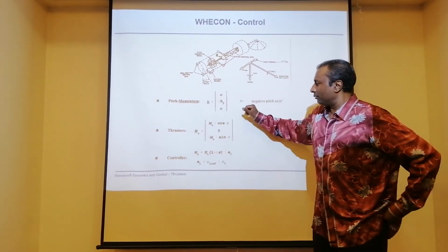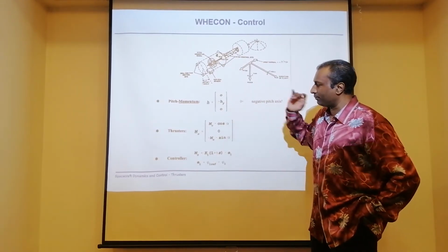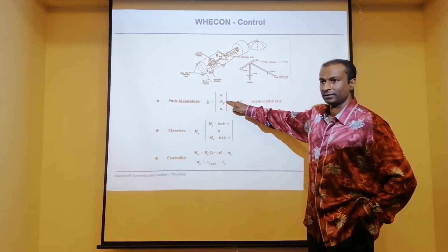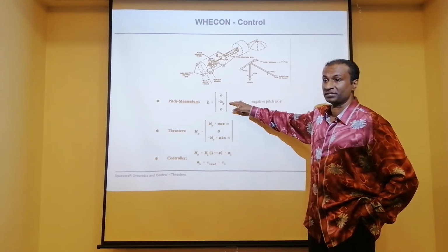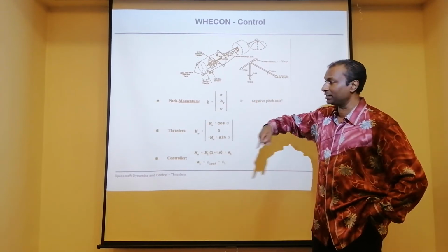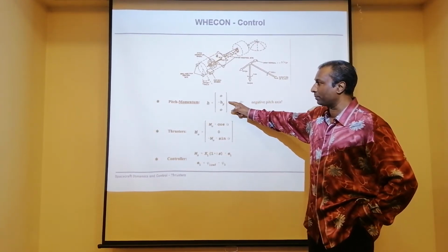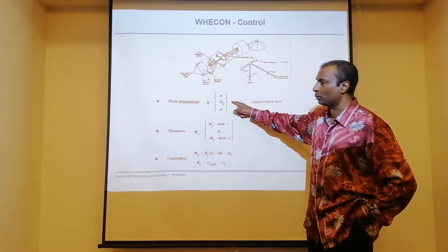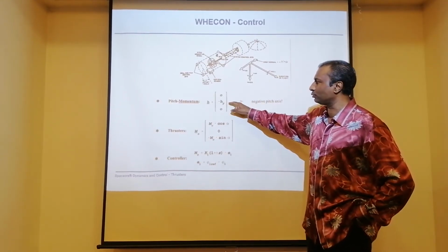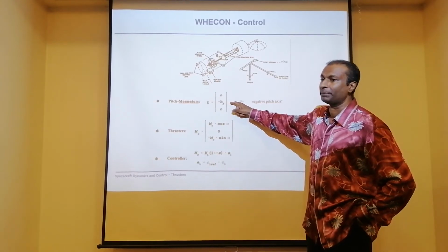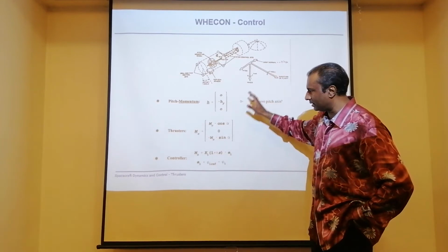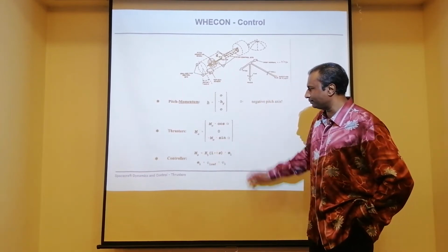So what it says is that, look, in order for me to have 3-axis control, I have pitch momentum taking care and giving me a gyroscopic stiffness, just like in my previous chapter. Plus, when I have a pitch angular momentum wheel, I should also be able to take care of the pitch axis attitude. Done. Pitch is done. Now roll and yaw.